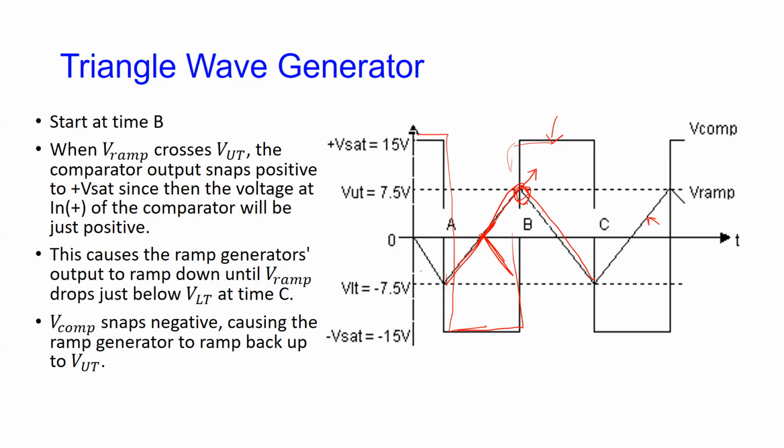And then, as I mentioned before, you could take the triangle wave and make a very clean sine wave. You pass it through a filter, one of the simple op-amp first order filters, and you put the triangle wave here. If you set a low pass filter for whatever the frequency of this is, it's going to pass that, and you're going to get a very nice clean sine wave coming out. So by adding a first order low pass filter, you can now get three waveforms coming out: a square, a ramp, and a sine wave.